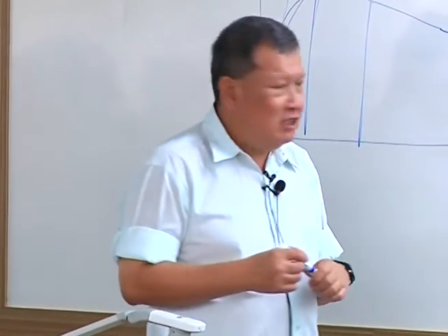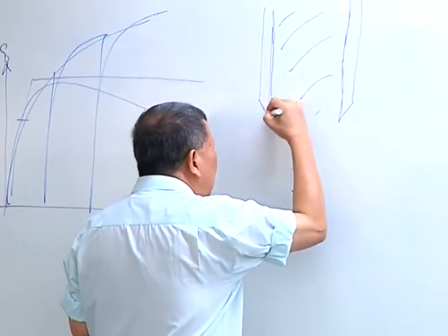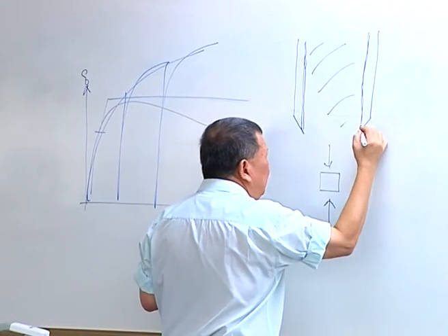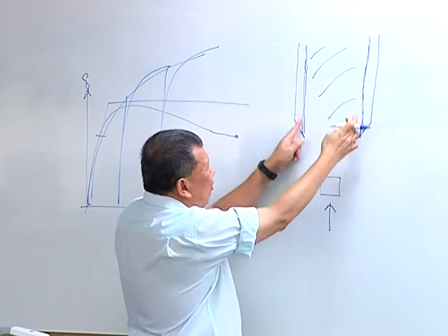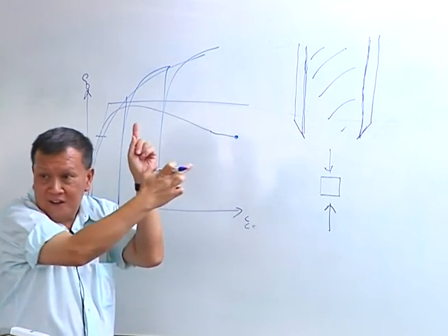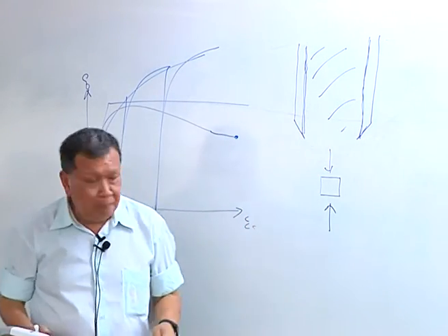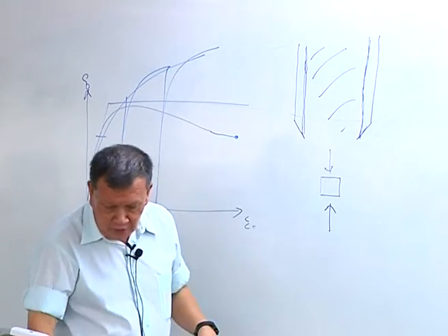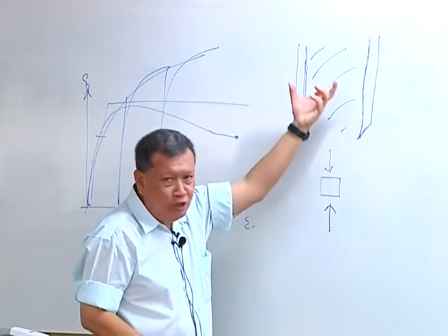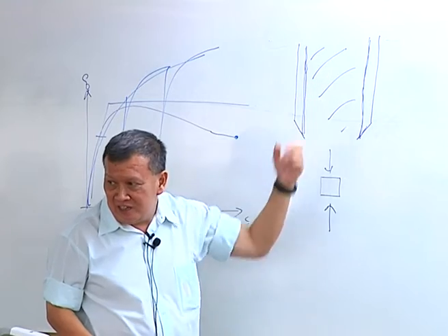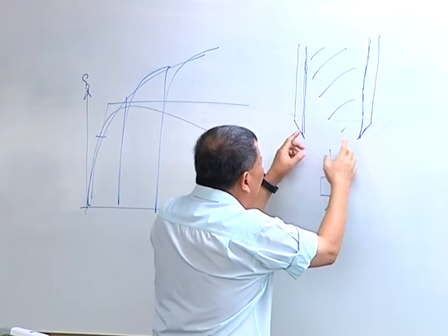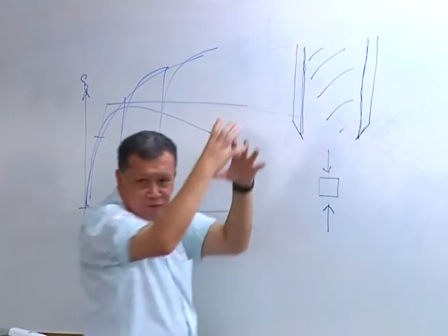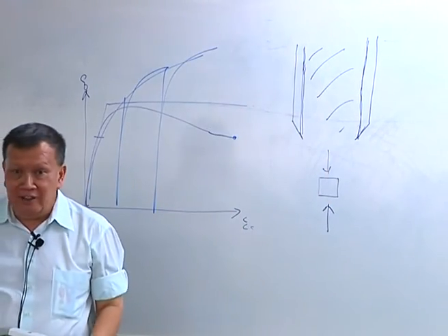The inner clearance says, around the tip here, I curve my tip in a little bit, so that the opening here is slightly smaller than the diameter inside. So you've got inner clearance. This is to lessen the tendency of the sample jamming, sticking inside here. So once the sample gets past this tip, it is able to detach itself from the wall and thereby